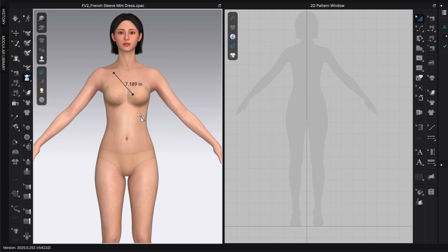I can also add a curved line, same way that we did in the garment pen tool by holding down Command and clicking and dragging. That gives us that red curve point. I can always add multiple curve points in a row by continuing to hold down Command, but that curve isn't going to be locked in place until I click one more time after my last curve point. Then I'll get another corner point, and I can continue adding more curves if I want, or just doing whatever with my pattern. I double clicked to finish that line.